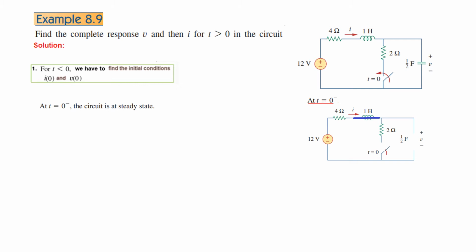Okay, so from here if you see what is the voltage here, you see 12 volt flowing and there is no outlet, circuit is not complete, so this is open. So we know that in case of an open, the source voltage will appear. So we can draw the circuit slightly neatly, same circuit. So V is 12, or V0 is 12 volt.